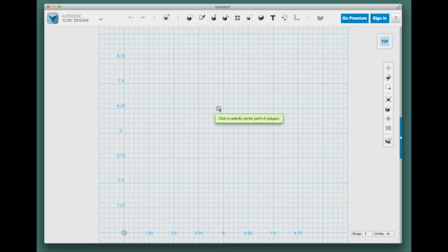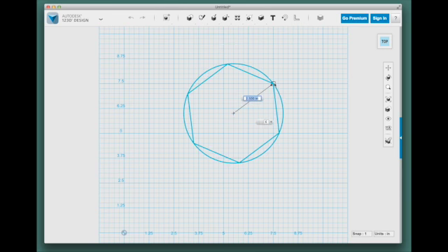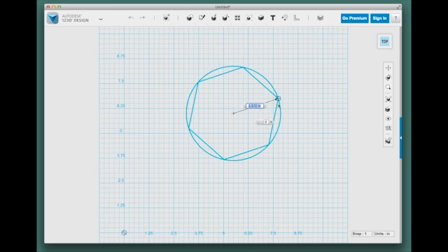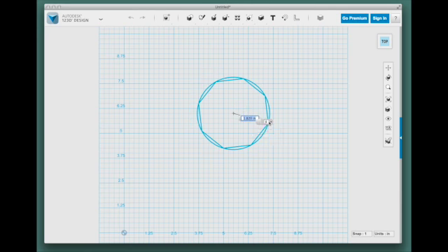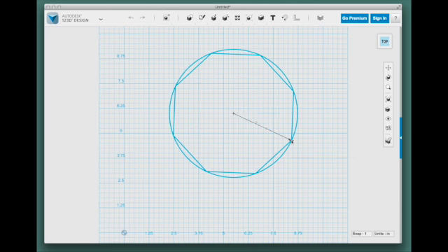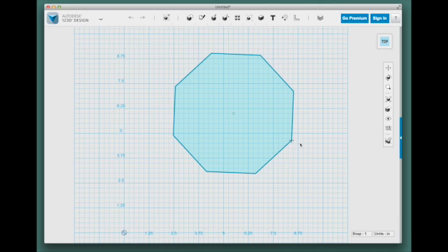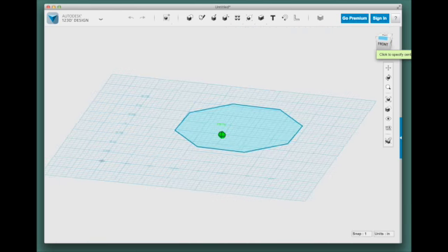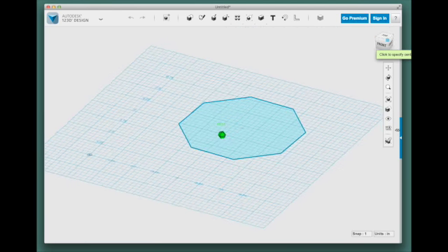In this case, I selected the tool from the top that will allow me to draw a 2D geometry object. It is drawing something with 6 or 8 faces, and you can change the number by putting in the number you want. In this case, I put 8 in. That gives me just a geometric shape, two-dimensional. And if I tilt the grid using the cube at the top right-hand corner to see it at an angle, you'll see it's only two-dimensional.